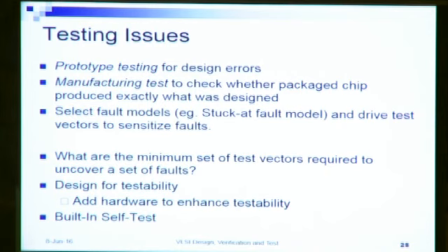So one of the very important issues in testing is to find out the minimum number of test vectors required to uncover a set of faults. We understand that any reasonably sized circuit will have an enormous number of possible inputs, right? So we cannot test a circuit for all possible inputs. The research here is to find out the minimum set of test vectors that are essential and can sensitize a given set of faults that we have. And we also have another aspect.